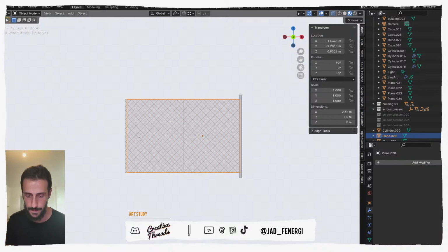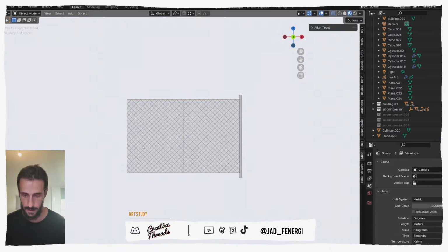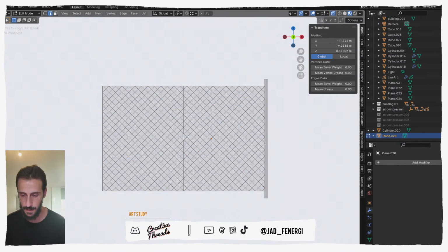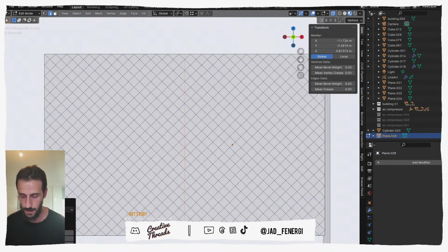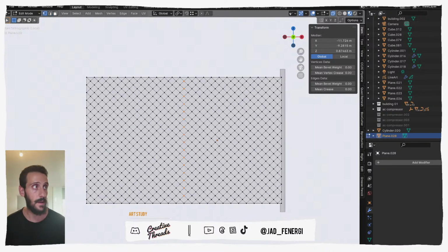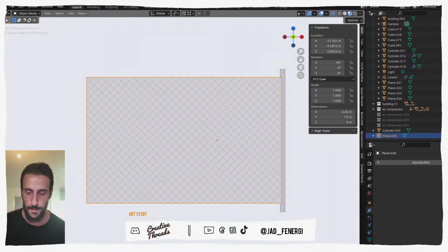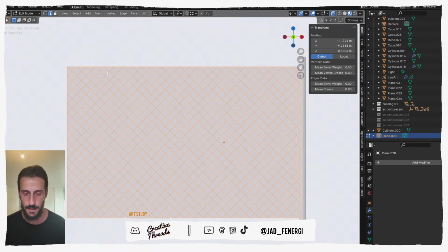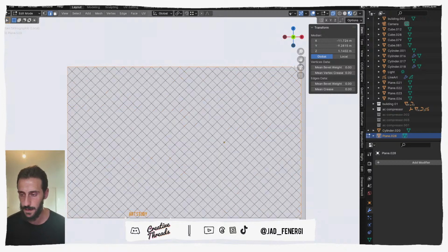I think it's collapse in 3ds Max. Then let's delete this. Let's go to edit view, then pick these faces from here, these edges from here till here, Ctrl X and dissolve. Alright, this is perfect. Now, what do you want to do? We want to select all the edges except maybe for the...